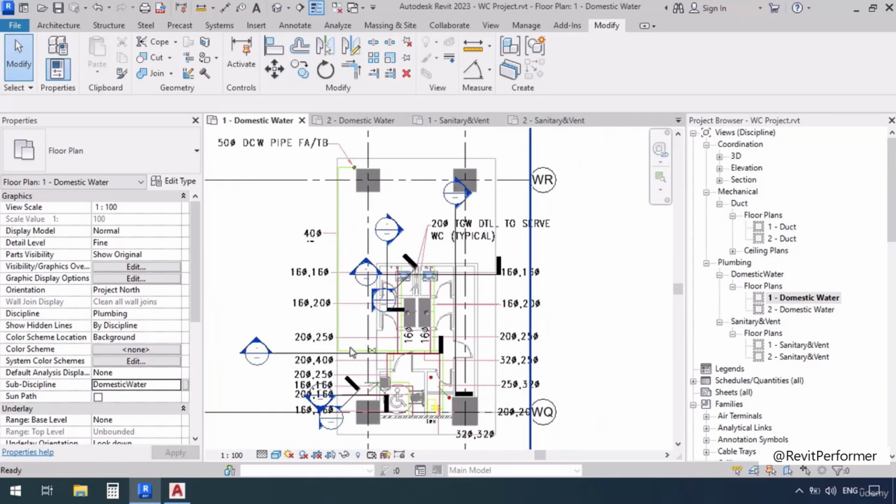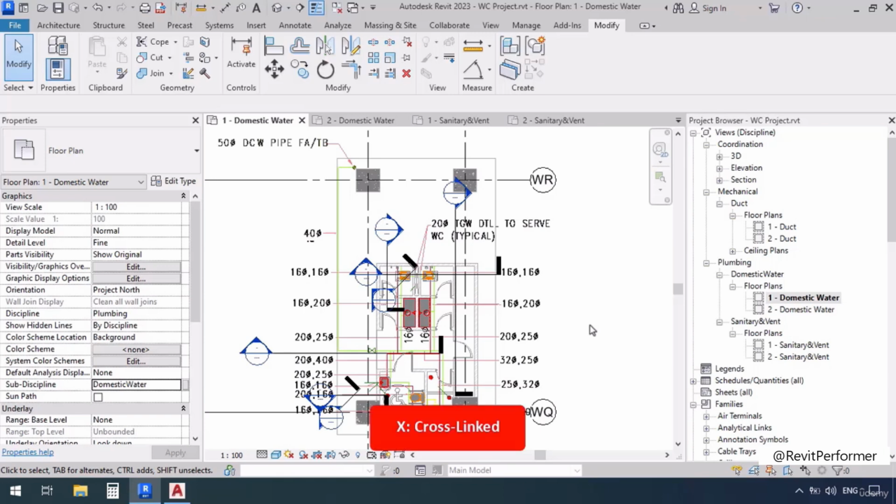Here we're going to want to draw our domestic pipes of the 5-layer pipe type. These 5-layer pipes could include different segments. For example, they can have PEX out PEX or PERT out PERT or any other segment. The letters PE in PEX out PEX stand for polyethylene, and the X stands for cross-link, as in this is the process through which that polyethylene pipe was created.